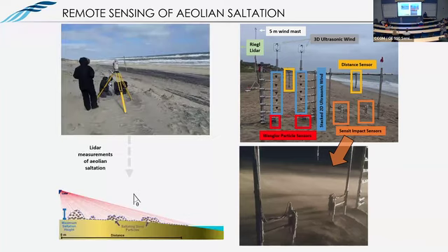And so we had the idea of thinking about how remote sensing maybe could inform something about the spatial and temporal magnitude of sediment transport. I think folks here are probably familiar with lidar technology. What we're going to do here is actually take a lidar, and rather than building a 3D scan of the room, we're going to point it in a single line and have it go back and forth as fast as we can. And by fast, I mean maybe 20 times a second we're measuring every point on the beach. And our hypothesis was that we could actually measure particles in the air with lidar.